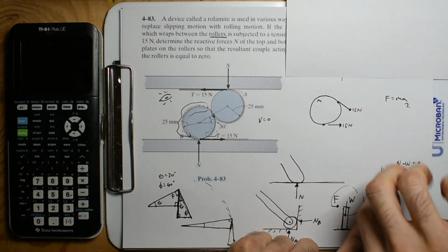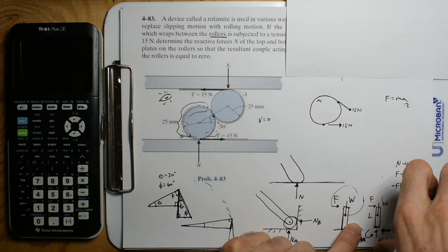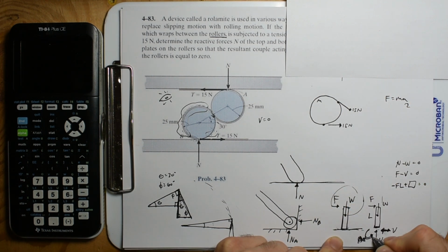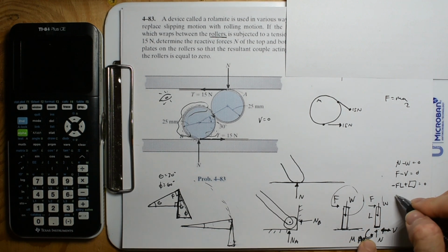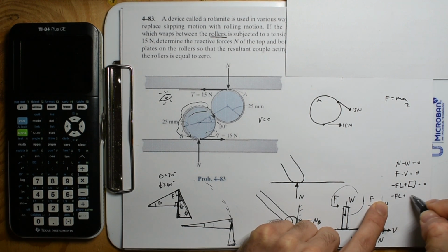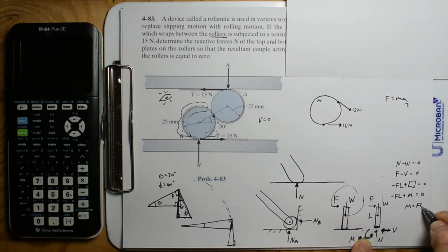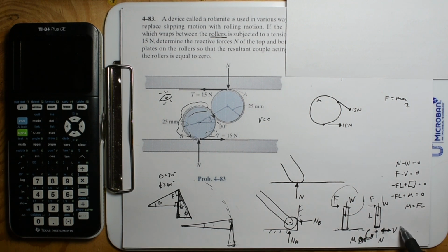If this is generating a negative moment, we have to generate a positive moment in that direction, which we labeled. So we have negative FL plus that moment M, and that has to equal 0. So this moment in this case has to equal FL. So those are the 3 reactions that are going to happen at a welded joint, where it's a rigid joint. Cool.